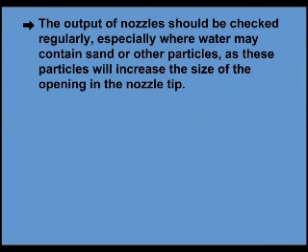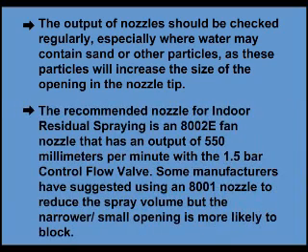The output of nozzles should be checked regularly, especially where water may contain sand or other particles, as these particles will increase the size of the opening in the nozzle tip. The recommended nozzle for indoor residual spraying is an 8002E fan nozzle that has an output of 550 ml per minute with the 1.5 bar control flow valve.